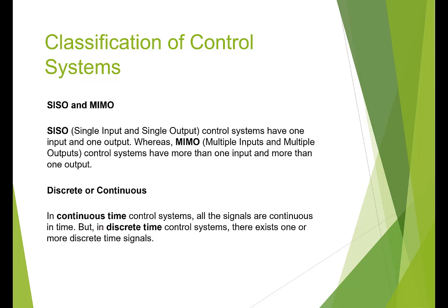And it's similar if you're familiar with digital and analog concepts. It's the same. A controller could be analog or digital. A digital controller usually looks at fixed time steps throughout the time, and an analog is a continuous time signal. Essentially, even if the robot has continuous inputs, the way we program it would be discrete, because in the computer everything would be digitalized. So even if we are using joint variables like this as an input, the way that the computer sees it is it breaks it into small discrete parts.